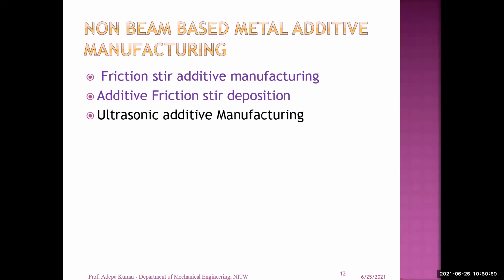In friction stir welding, you are joining similar or dissimilar materials with the help of friction. The friction is developed between the tool and the workpiece. The tool is rotated with a certain RPM and the workpiece is stationary. Due to the friction, heat is generated. That heat is utilized to soften the material and leads to joining of these two materials.